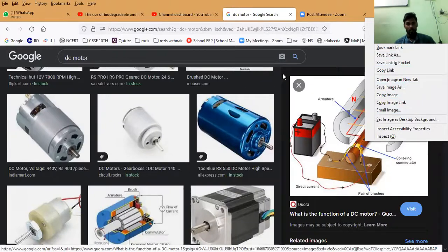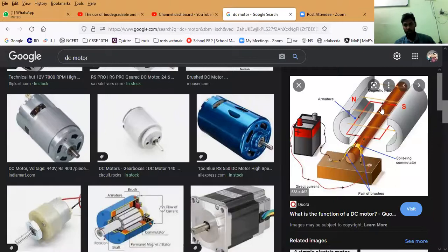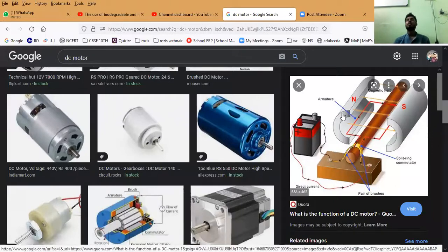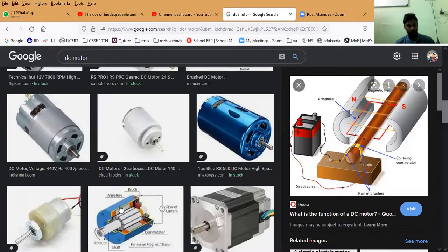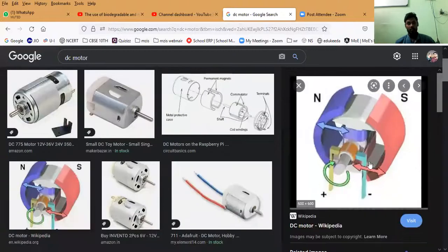Okay. Now if you notice it, guys. So this is what you will see. The rectangular coil, and the rod in the middle which you are seeing, that is only the axle, we can say, or the shaft. Okay, so now if you see, every half rotation, this X split ring will go to that side, and that Y split ring will come to this side. So the position of the commutators keeps on changing every half rotation, so that the DC motor is continuously rotating. So every DC motor is like this only. You can notice it. Inside you can see this is the position.